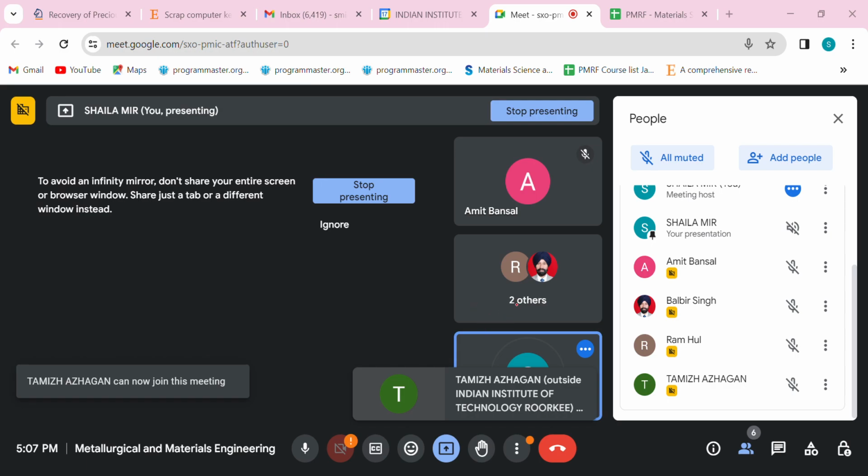We saw that. Then we have conical shaped steel with 120-degree apex angle, conical shaped diamond with 120-degree apex angle, and 10 mm diameter hardened steel balls. Obviously, this last one is also not true because this is a Brale indenter, not a steel ball indenter, which is for Brinell or a scale B type of indenter. So now you have two options. Which of the two is right? Is it a conical shaped steel with 120 apex angle, or is it a conical shaped diamond with 120 apex angle?